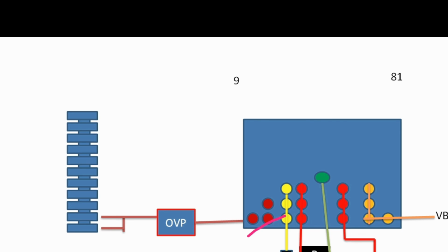Check the boot cap also, right? Also check the input voltage in this IC. Mostly if you change or replace this IC, 100% your problem is solved. But on the other hand, if the problem is on this side, this side goes to the PMIC and many other sections in the mobile phone, right? For this, you need a thermal camera.